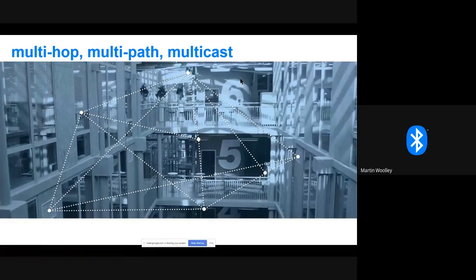So I could choose to have one of the lights in my room configured to act as a relay. A relay is one of the special roles that a device can have. And any device that's a relay will simply rebroadcast, repeat, any message that it hears from one of its neighbors. One of the things that makes using Bluetooth Mesh different to using Bluetooth in other ways is that there is a network design requirement. We don't tend to think too much in terms of network design when we're dealing with connectable Bluetooth low energy devices where they're forming point-to-point, one-to-one connections between two. There's not much else to think about in that respect.